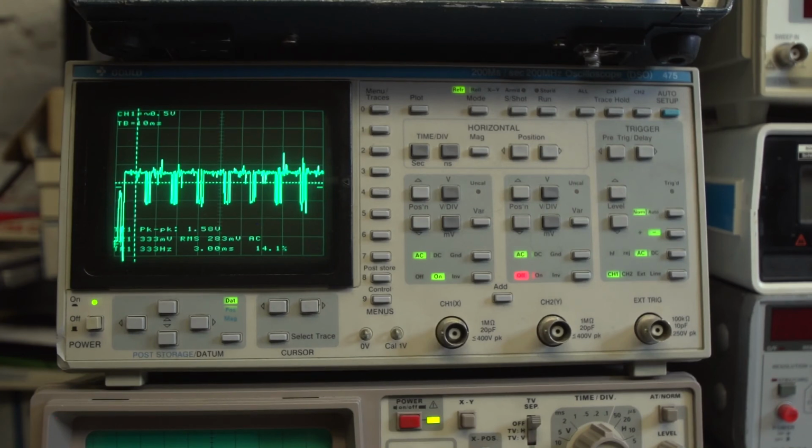And you can get interfaces that plug into your PC, an interface box where it's all done in the computer and it gives you a nice digital display. You can also get LCD or OLED display versions now from various manufacturers, and they do all the inbuilt mathematics to calculate RMS, peak to peak, time interval and frequency all in the box. So these ones are old, but they give you a good idea how the modern ones work, and an appreciation for the old CRT technology as well. And there are plenty of them around.